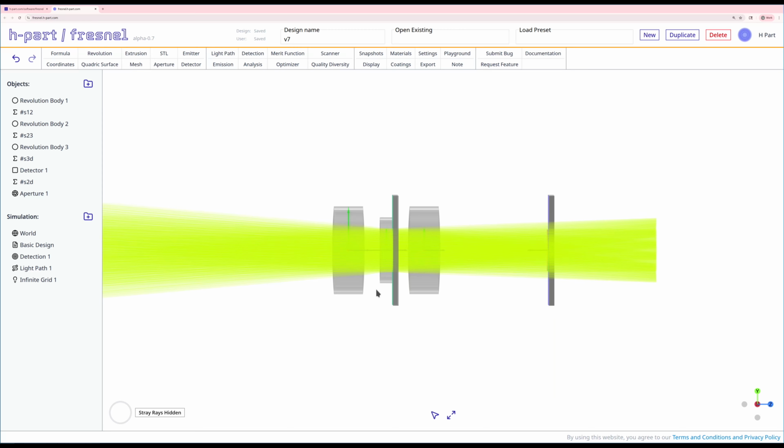Explaining how paraxial analyses work is a bit beyond the scope of this video, but suffice to say that they are much faster to compute than full ray tracing based analyses. However, they tend to be approximate. So they're very useful for quickly getting the optical system into the right position. And then after you do that, you would create a ray tracing based merit function and then fine tune it with a ray tracing optimizer, which would be slower but more precise.